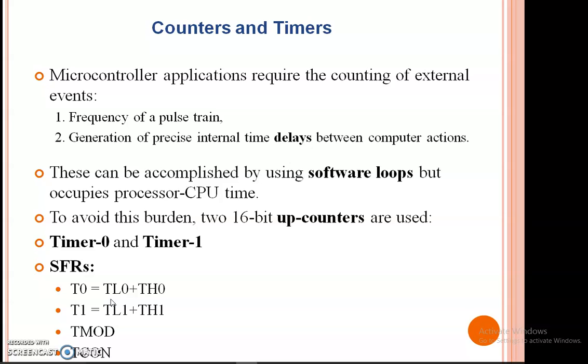Delays can be produced by software loops also, but when we use software loops, CPU time is required to execute the software loops. To avoid CPU time utilization, we can use the timers as hardware timers.